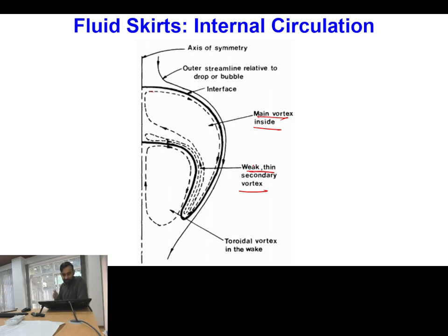But why is this particular vortex shown in the reverse direction? Just to balance the tangential stress condition at the boundary. So theoretically tangential stress should balance at the boundary. So that's why if in the surrounding fluid some toroidal vortex is forming, here also we should have vortex formation in the opposite direction to the main vortex, then only our tangential stress condition will be balanced.